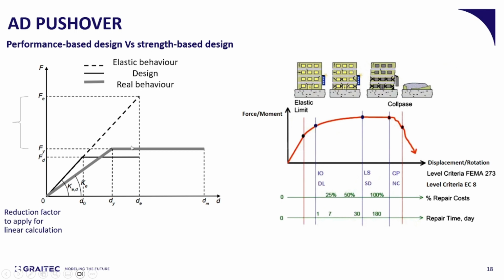The maximum force the structure will be able to develop is the Fy, which corresponds to a force that is smaller compared to the Fe, which is the elastic force we would get if the structure behaved elastically. And of course, we have this curve, which is different from the real curve, and is basically the one we take into consideration when designing.